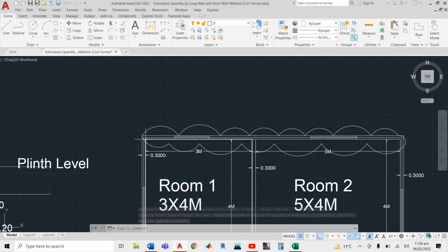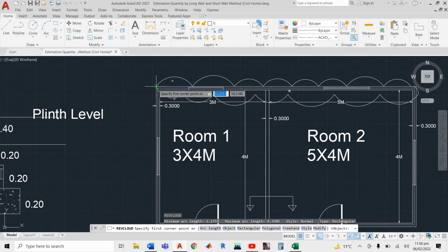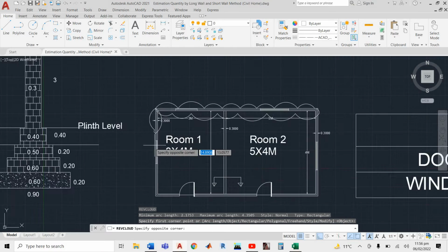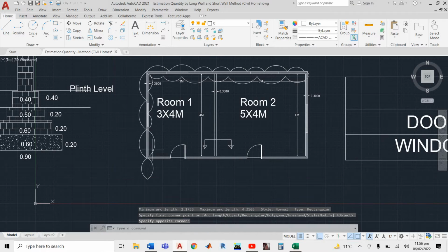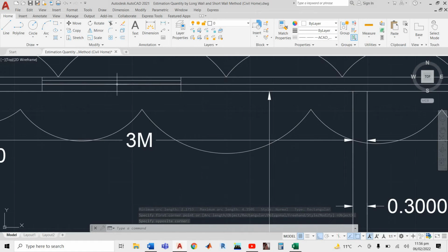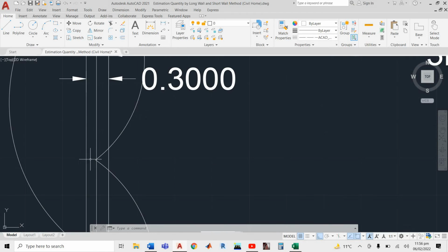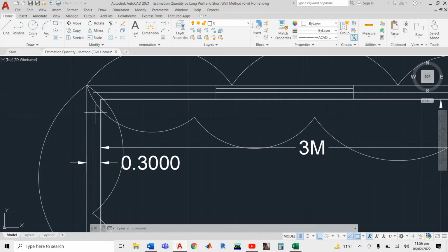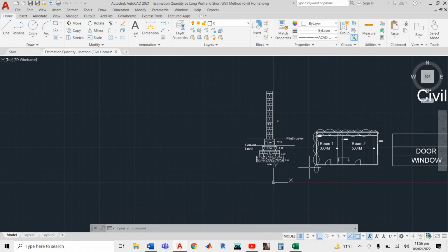You have to excavate at the center of the wall. And if I also define this foundation in the vertical wall like this, we have to get the center of this. Because of this, I already drew the center line on each boundary of our house plan.